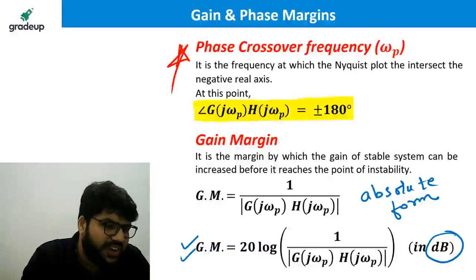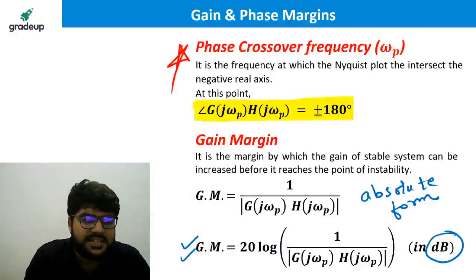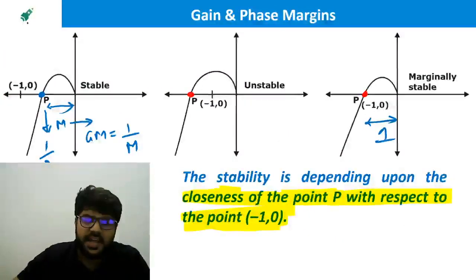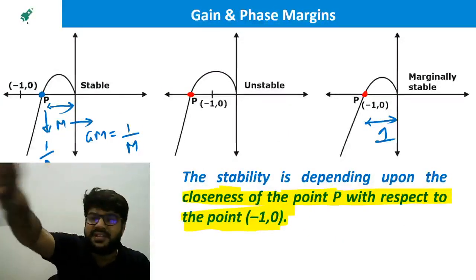Yeah, definitely, Anu. Vice versa, you can also think you can make an unstable system stable by decreasing K here. If I talk with this example only, you can decrease the gain so that you can make the system stable.